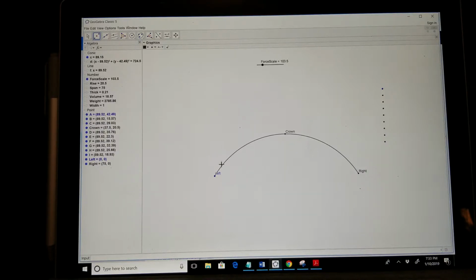Now I want to discretize this strip into 8 point loads, and I will use the discretize, or the midpoint button again, sorry, between the left and the right. And I'm going to do that a couple times here. Not just a couple, but I'm going to do it 8 times to get 8 segments. Okay, now we're nicely done.